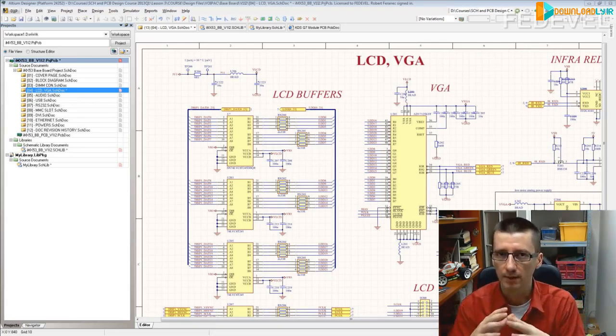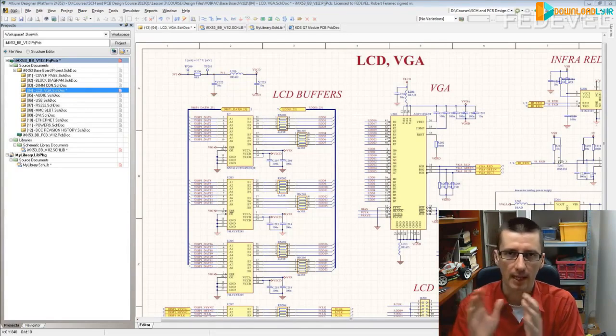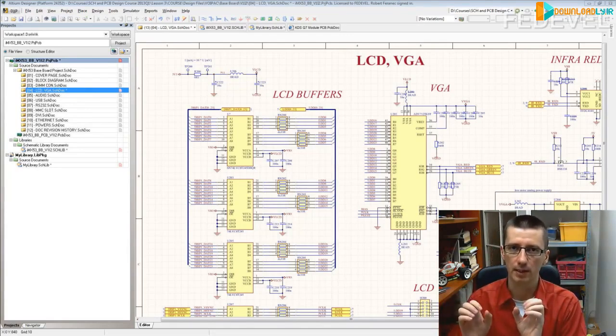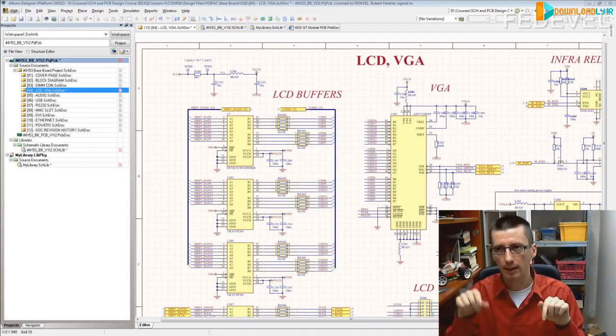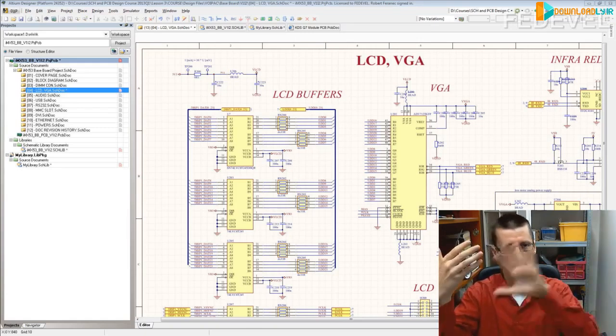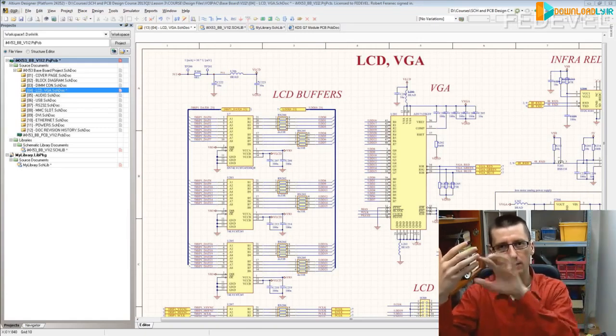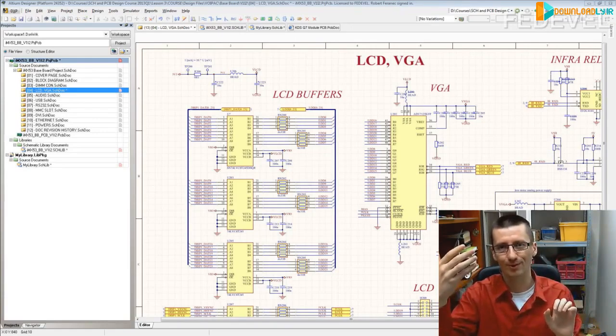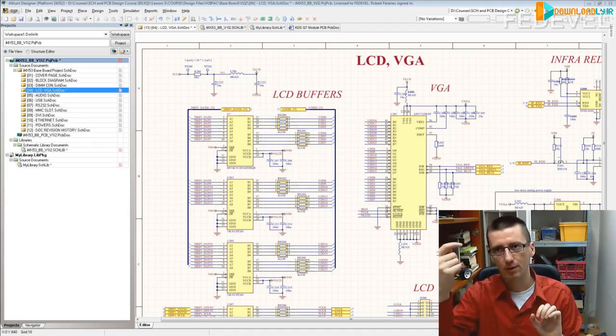And of course, I don't mix digital and analog signals. You know, you have a board, and in a small corner I have the analog, the audio, for example. I try to have it only on one layer in the corner, yeah? Not one layer on the whole board. In the corner, I use only one layer for the analog components.